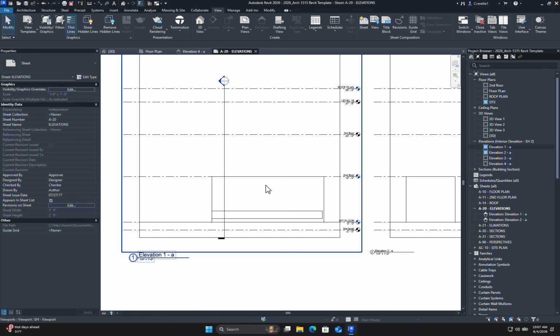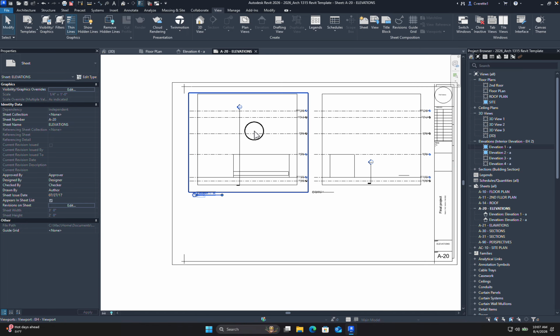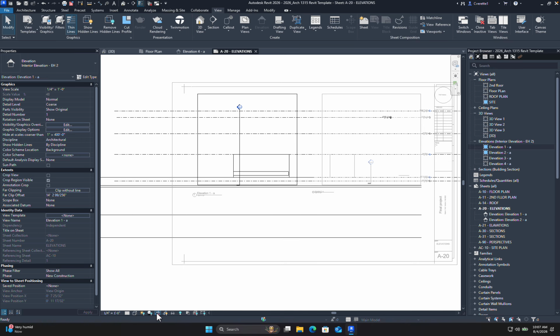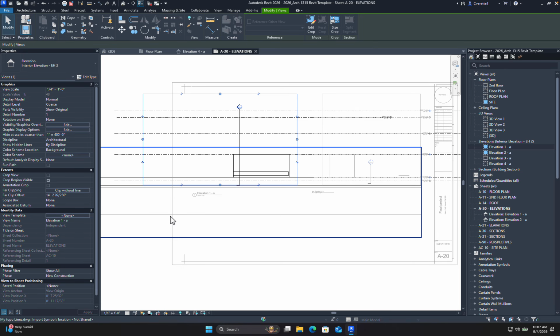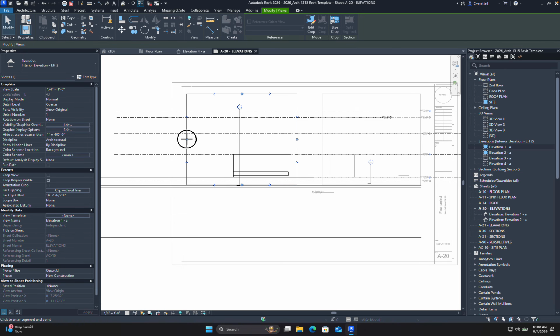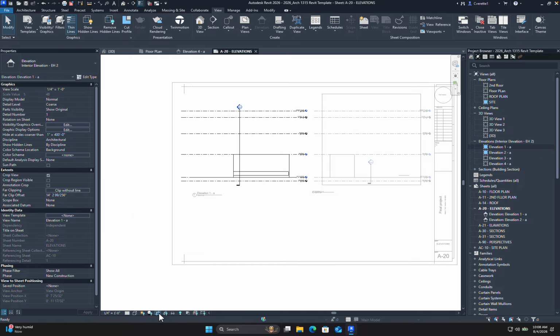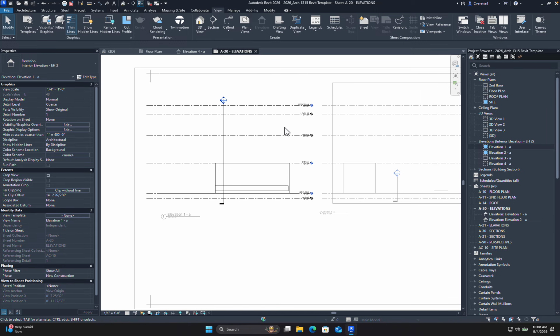In our case, you'll also know that there's a bounding box by default. I can double click on here, and there is a button that controls that. So you'll see that there's a crop view, which actually controls the rest of the drawing. So I can actually uncrop it, if I wanted to see more or go, oh man, I actually need a little bit of that part involved too. And I can control that pretty separately. So this is basically a frame and the crop tool. I can turn that off, and I can turn the actual frame off as well, right? So if you wanted something to look a little bit more realistic.